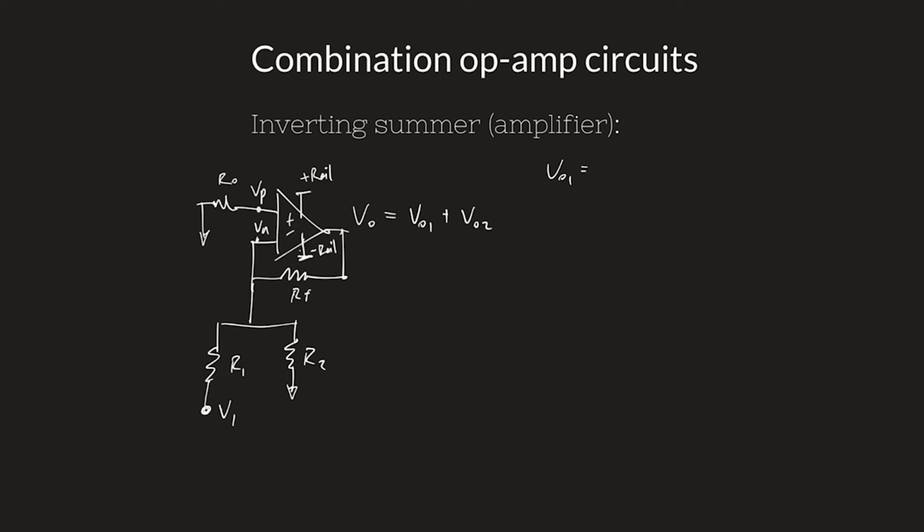So remember that VP always equals VN. That's because of negative feedback. IN always is 0. That's because it's an op-amp. So no current here, no current here. These two values here are coupled. So that means VN at this point in this circuit has a ground there. It's got a virtual ground because VP is actually grounded. So if I'm grounded right here at this node, this whole node here is 0.